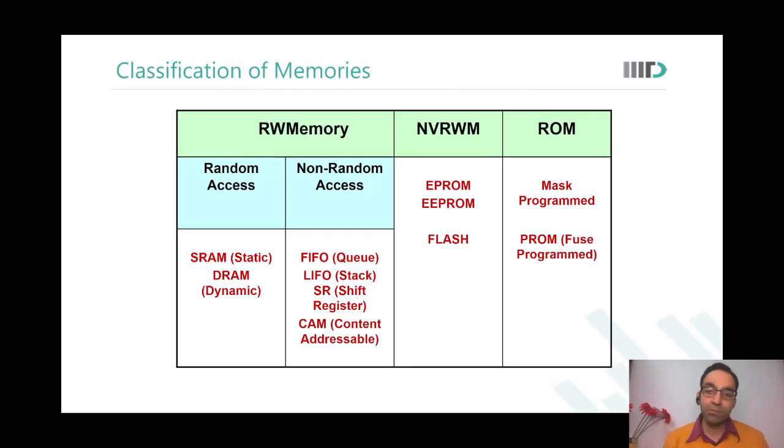When we are saying mask programmable or mask programmed, it means that at the time of designing the mask for that particular chip, I already decide what is the data that needs to be stored. So can you ever change the content of a mask programmed ROM? No, sir. No. Because it is mask programmed, we are already preempting what data needs to be written into the ROM. It is much, much denser than EEPROMs.